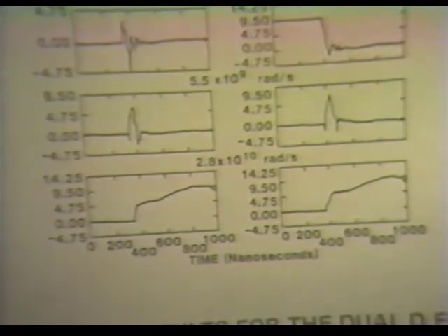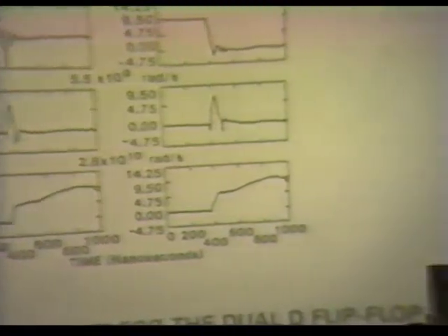You know, the node capacitance somewhere is just right, so that finally these devices that were low end up going high. You really don't know how that's going to turn out unless you know all the fine details of the layout of your circuit. Because when you overwhelm everything with charge carriers, it may take something like 1 picofarad difference in node capacitance somewhere, and that may mean that it comes up this way every time after you do that. You never know, but it only takes a small amount of some circuit parameter to determine which way it goes.